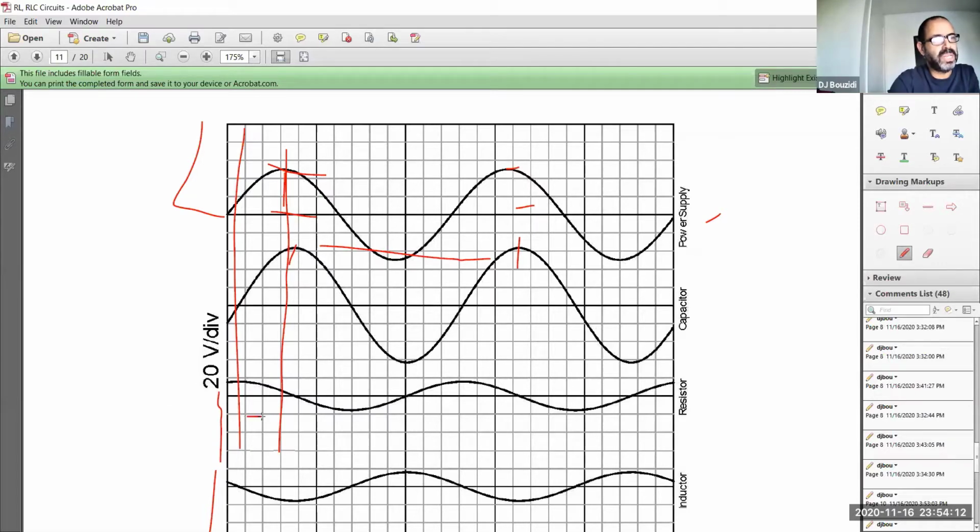So what we're measuring is this phase difference. That's where phi is, and it's going to be a negative number in this case, at least that's how it looks to me, unless you guys disagree with me. So the voltage is actually ahead of the current, or the current is lagging behind the voltage. You need to find this difference, that is delta t, the difference in time.